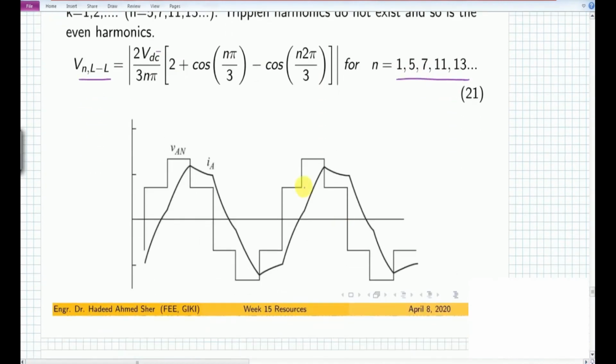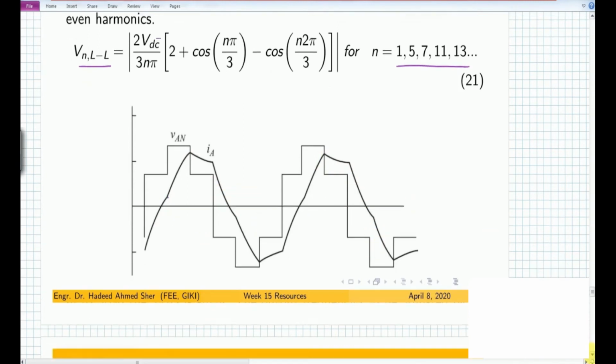For this particular waveform where we have the current available, the current will have to pass through the switches, and as you can see here, there is a slight delay in the current owing to the inductive nature of the load. When we have a positive VFN supplied, the current rises from this particular value to this particular point. This curve depends on the ratio of the inductor and resistance, and the same goes with this VFN. So we have a current shape which looks more like a sinusoidal waveform owing to the inductive property.